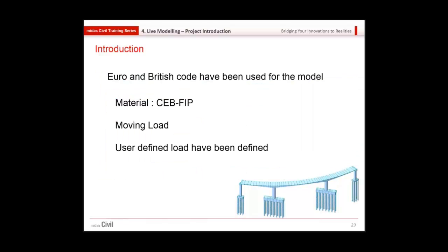And this project has been done using Euro and British codes, and for the material CEB-FIP code has been used. And for moving load, as there are special vehicles for this kind of metro in Indonesia, they have used a user defined vehicle for this model.